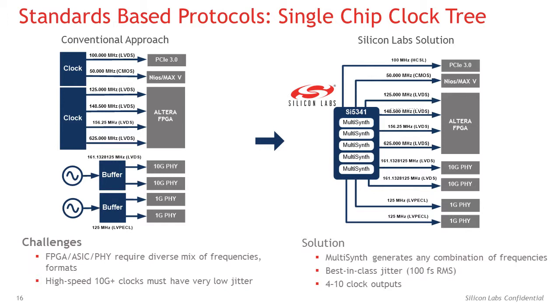What Silicon Labs tries to do, and in our partnership with Altera, why I believe that we work very well together, is we're very good at developing technology that with a single chip or with fewer chips, you can actually hit all those different frequencies, whatever they are, from PCB to one application to another. Be able to hit all of those and still hit all the phase noise requirements, all of the jitter requirements, all of the accuracy requirements that are demanded to really take advantage of the high performance that you would work with, for example, in a Stratix 5 FPGA.